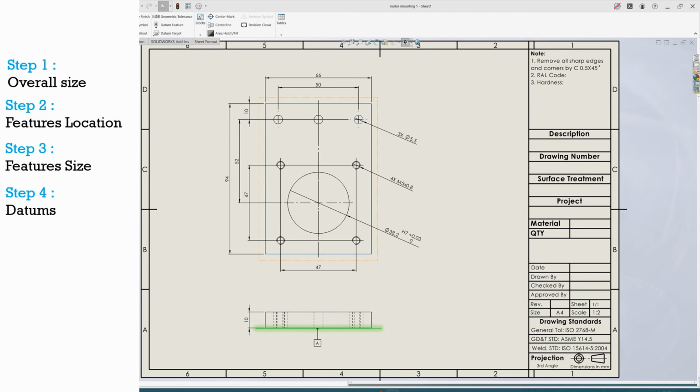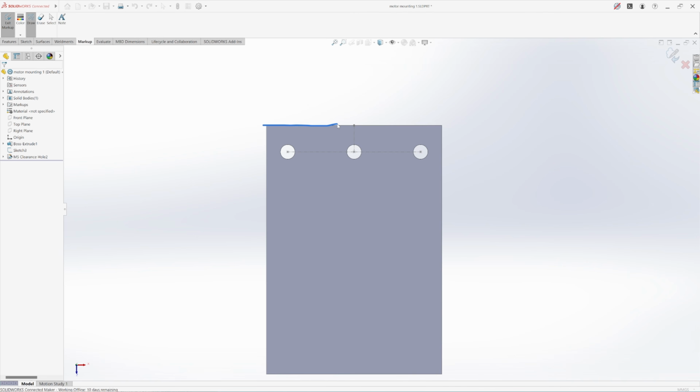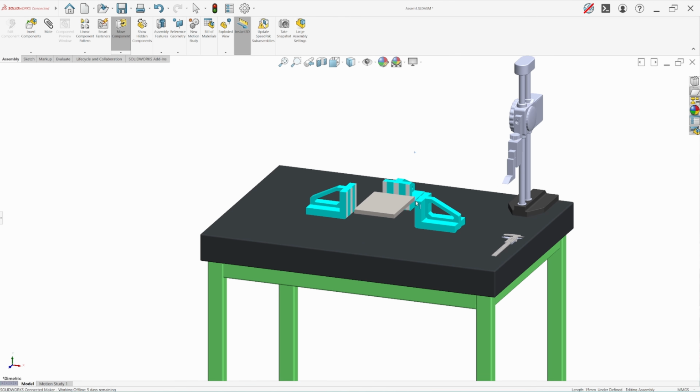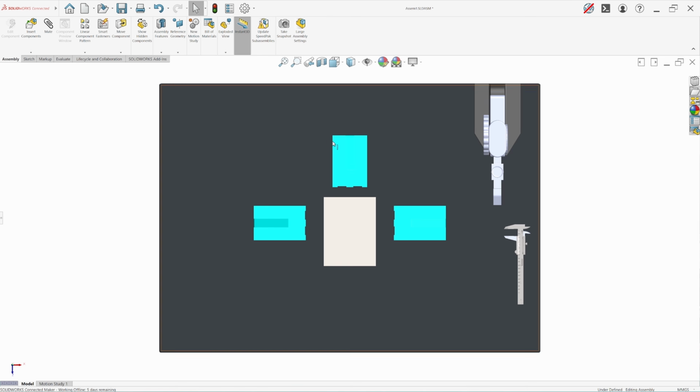So the bottom face is our datum A. And as we define the position of the first feature, these plate mounting holes, from the top side as a reference, after resting the part at its bottom in inspection or manufacturing, we can constrain this face at a right angle as a setup intent.